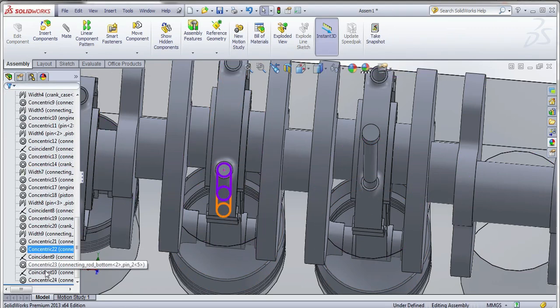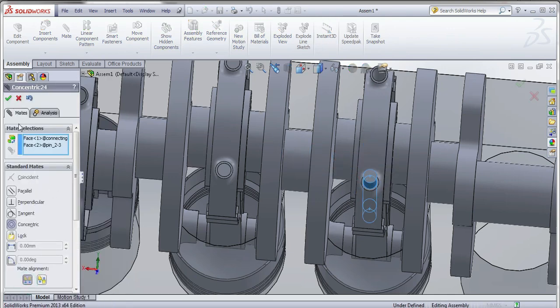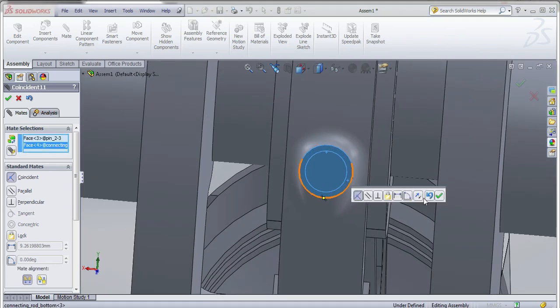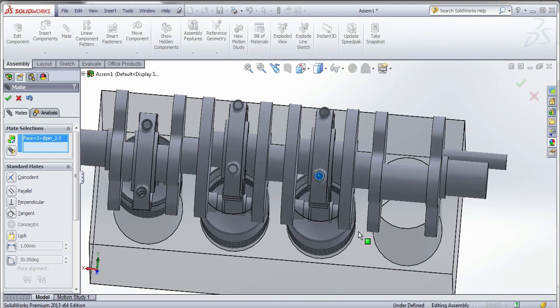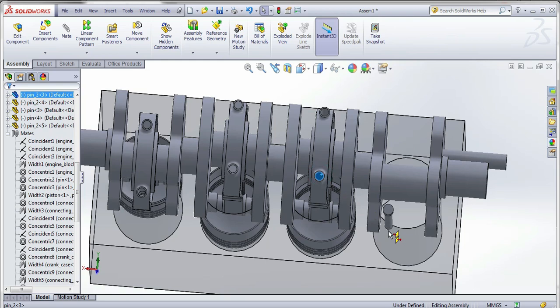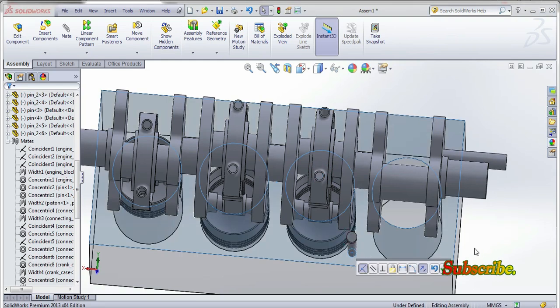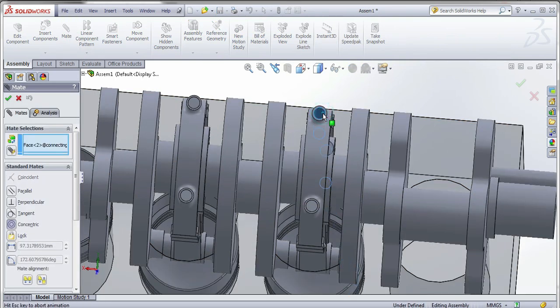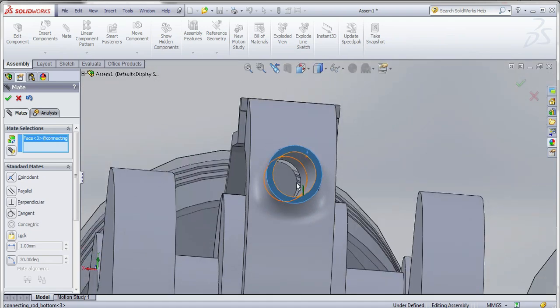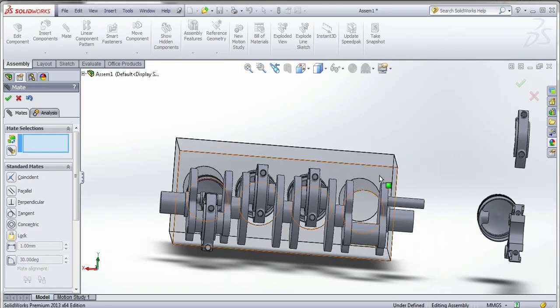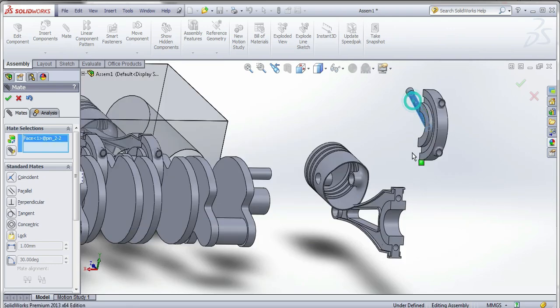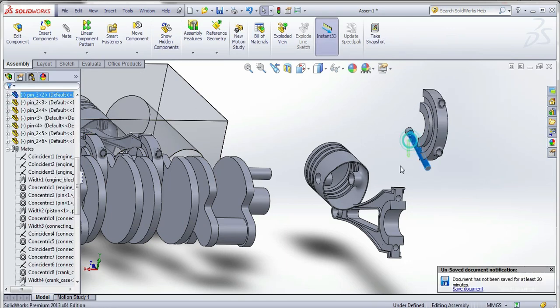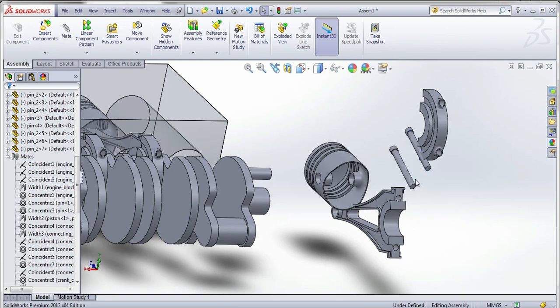I want to flip the last one. I want to flip and then top surface to top surface. Same one. Exit mate. Click, left click and drag. Click plus Control command. And select the top surface to this bottom surface. Okay, the last piston I'm going to assemble. Just click, Control plus right click, just go to drag, we copy, mate.